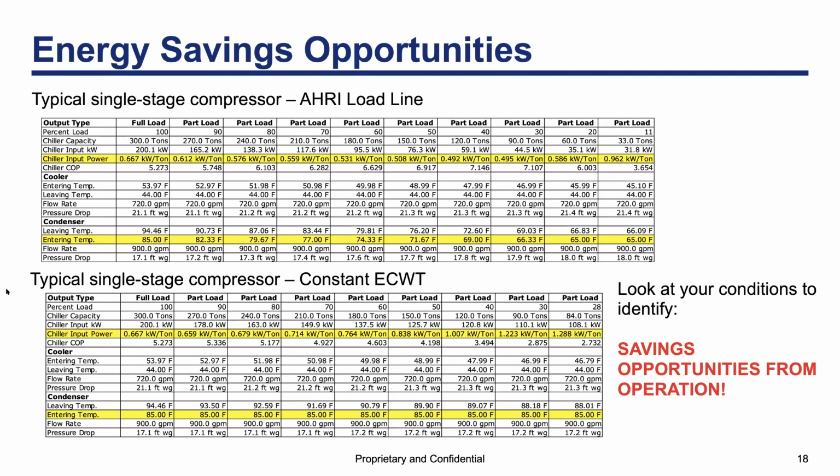I know that in some states here in the US and some other countries around the globe, electricity is cheap, but in some others, electricity is very expensive. So I assume 12 cents per kWh and 3,500 hours, which is equivalent to 40% of the total hours in a year.